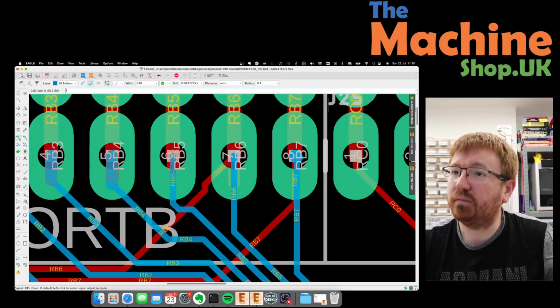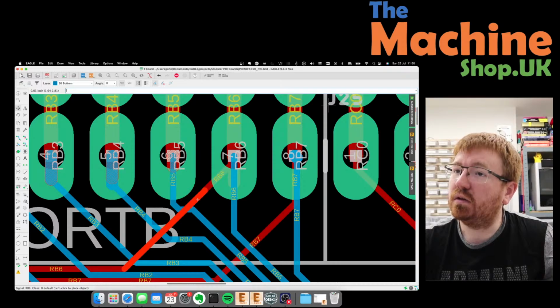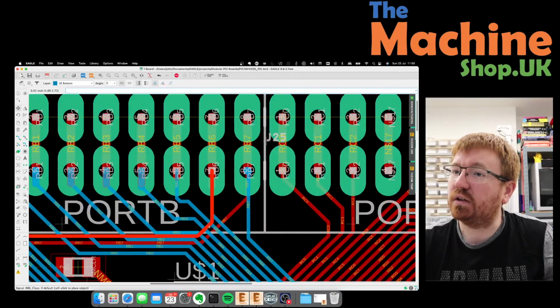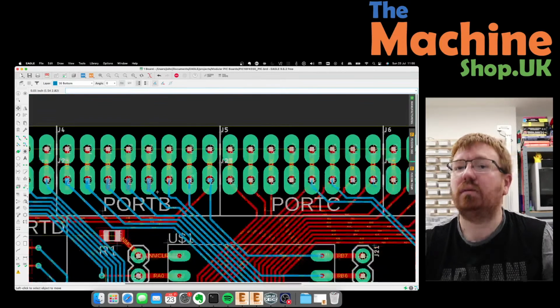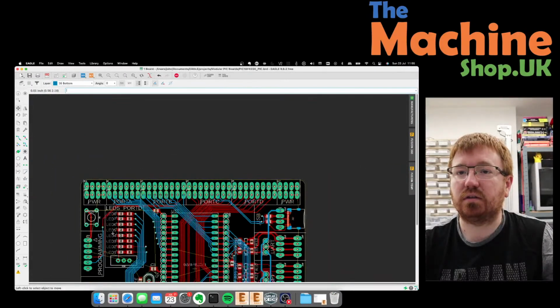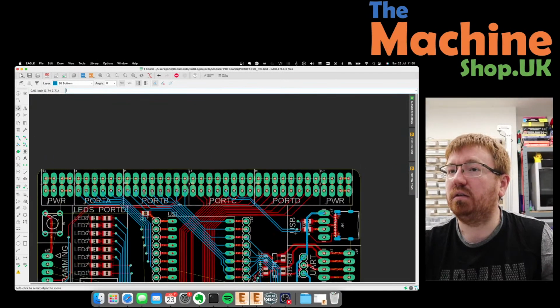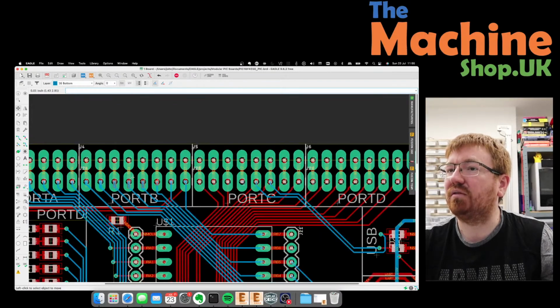That'll do. Whilst I've just spotted that RB6, let's just neaten that up, if I can. Let's see if I can get it to grab. There we go, and come out something nice. We'll go and join RB7. In fact, let's do that one close to there. Let's do RB7, RB6. Those two are the programming lines that go to this programming header over here, so they're kind of crucial to get right.